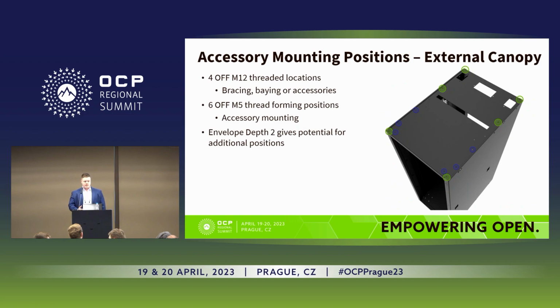Okay, so additional to front and rear, there's also opportunities on the canopy. So there's a requirement for M12 fixing positions in the canopy. Again, this can be used for seismic, fixing it to the structure of the building or the data center, and also baying racks together.